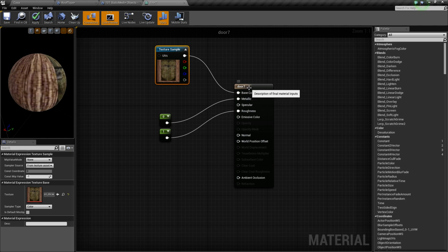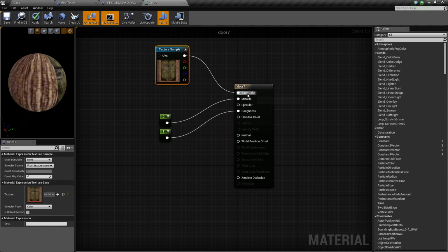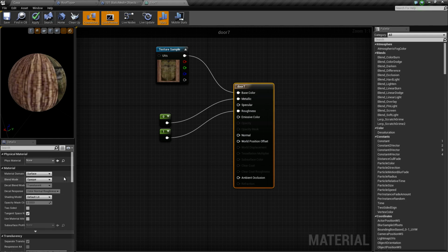Material wise, there are lighting options. This is something to be aware of, particularly if you're going to be using opacity type masked materials to create object surfaces. You should toss that idea out the window and replace it in favor of actual geometry. There's no need to do the old fake-the-object-with-a-mask trick anymore.